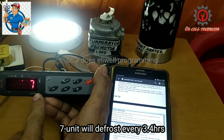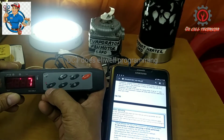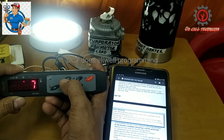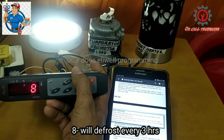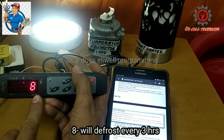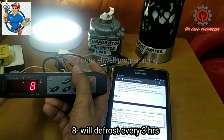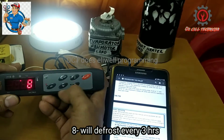Every 3.4 hours, the electrical heater will activate. And if you set it to 8, the 24 divided by 8 is 3. So every 3 hours, the electrical heater or the hot gas will activate.